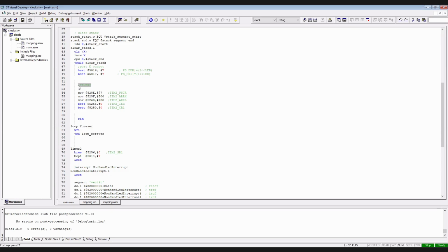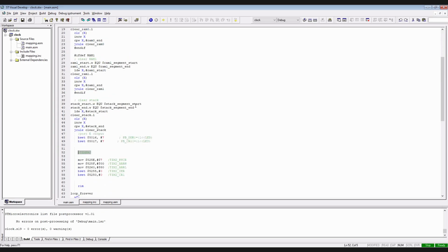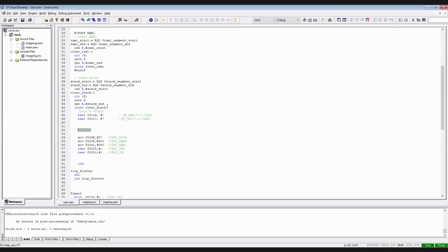The timers take their clock source from the main master clock, which we set here. But they can also be prescaled in order to lower the clock frequency that is counted.